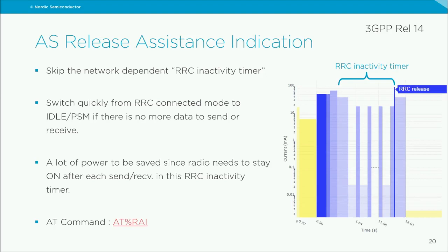And this timer can have a huge impact on your overall power consumption because this is very different from network to network. Some networks have 4 seconds and some networks can have up to 15 seconds. And a worst case scenario, I've seen even 60 seconds. So that means for each time you send your device, you need to have your radio on just listening to the network if it has some more things to send to you.